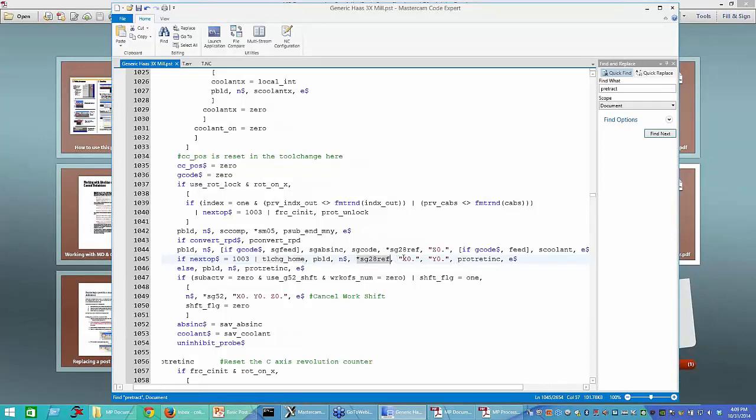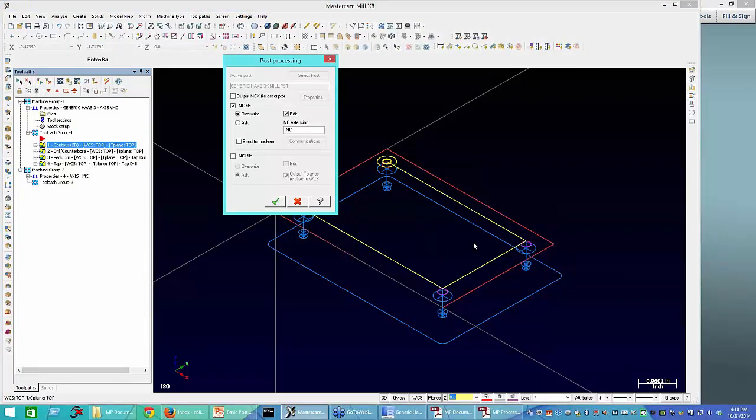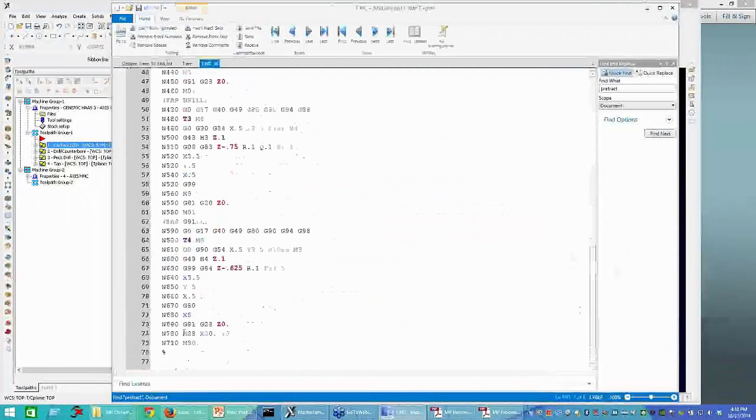and then if this equals 1003, or we have this switch turned on, we're going to output G28, and then we're going to output X0 or Y0, or, say, X30 Y-20 because their machine has a funky coordinate system or something. But if you want to modify the end of file, it would be this line in P retract. So here I'm going to save that as X30. We'll go, and if we look at the code that's generated, we get down to the end here, and now we're going to get G28 X30 Y0 X0. Good question, but that's where you control the retraction, in P retract, and you can also hard code stuff into the PEOF. But again, we're doing our basic post class because it's stuff that's common, that people often want to do, changing the output of their post.